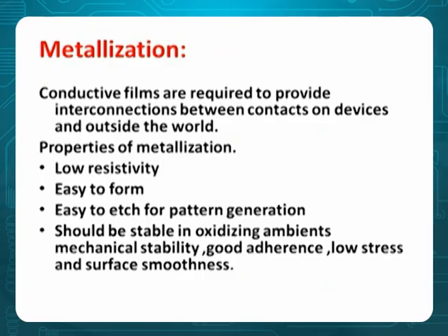Next one, metallization. What exactly is metallization? For example, you have made an IC completely, but suppose there are so many components, and you want to connect one component to the other component. We need metallic contacts. These metallic contacts are definitely required, and they also provide a connection from the component to the external world. Wherever you are using this application, you need to connect it. Therefore, all the chips which are inside should have metallic contacts.